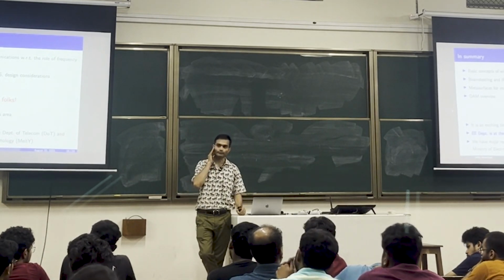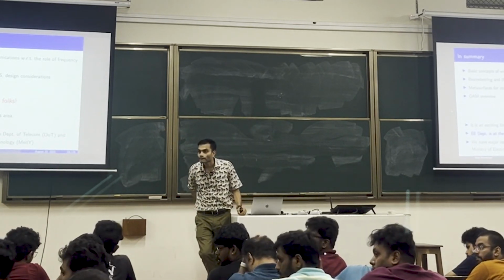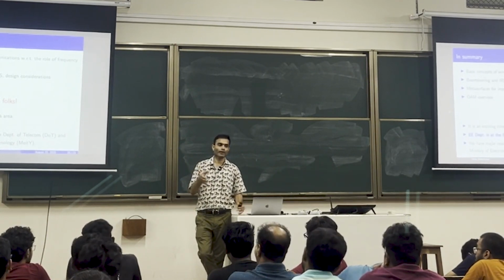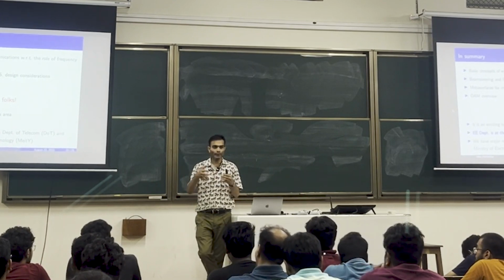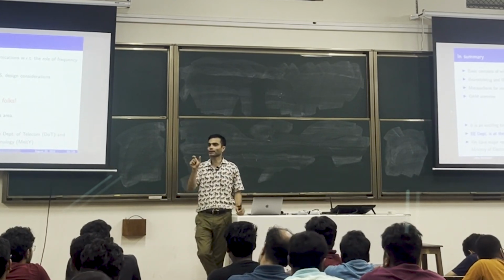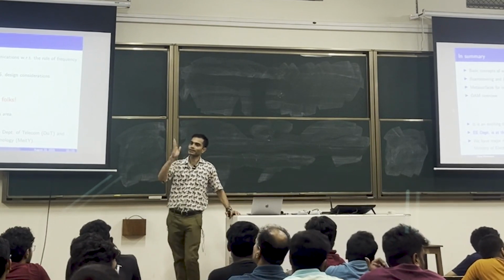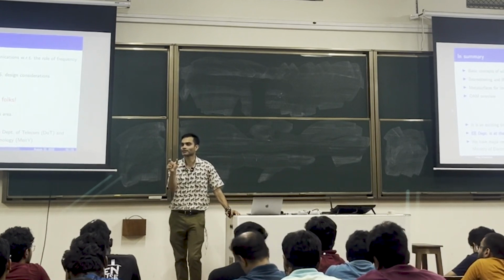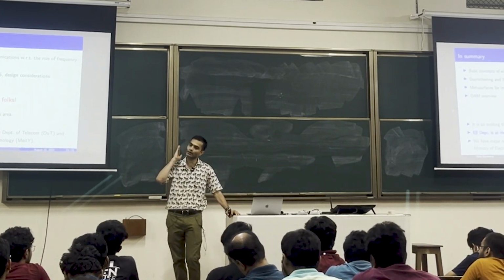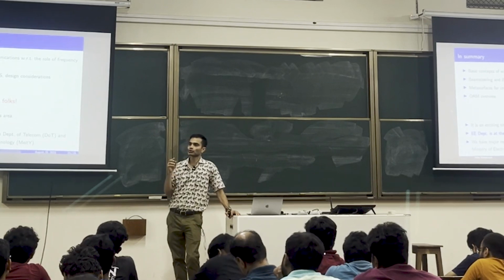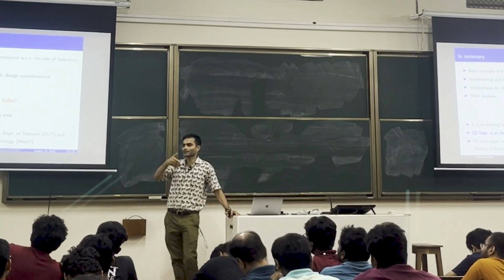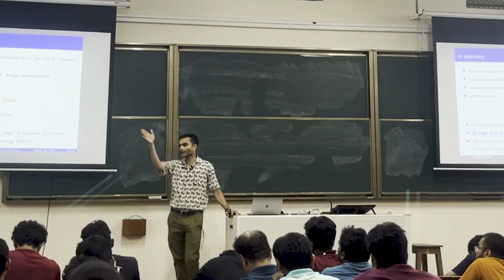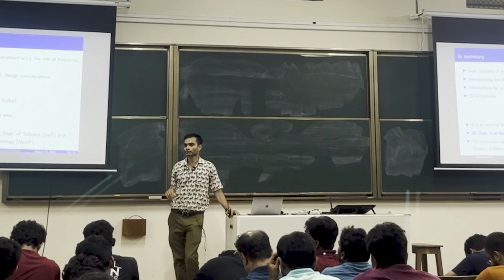How do you know where the user is? Part of this is the protocol. If you look at the way people do OFDM and all of these, there are certain periods of time where the user just sends a pilot signal, and you are looking for a user in that period of time. The first 10 microseconds, the first 20 microseconds, they just send a tone, a sine omega t. So on the IRS, as I mentioned, direction of arrival algorithms can figure out from this entire space where the user is, right?